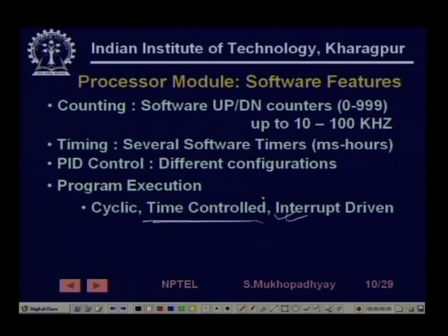There are some tasks which can suddenly occur, like failures kind of tasks, which once they occur are not taken into consideration of the regular computing flow, but once they occur they are required to have very high priority, and therefore they have to immediately get the attention of the processor. So, such tasks are sometimes coded in the interrupt driven execution mode. So, whatever the processor was doing, it will be interrupted and this requirement will be catered to.